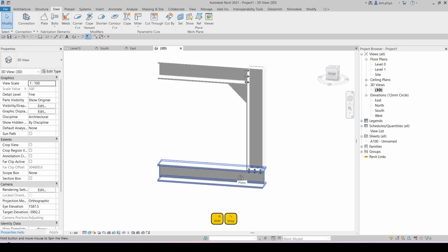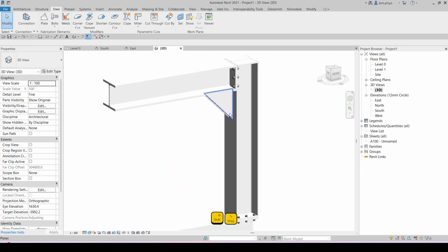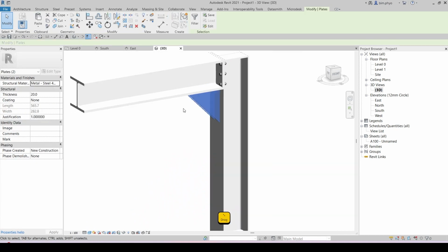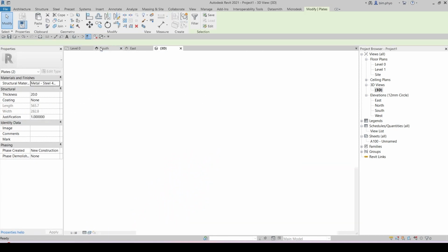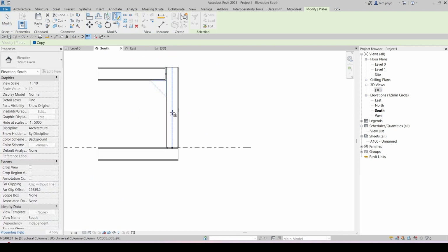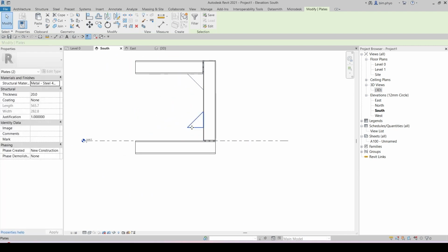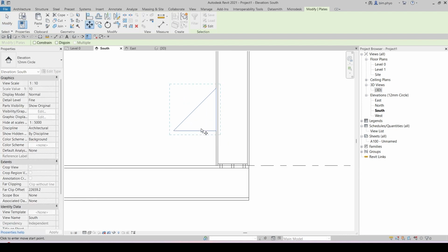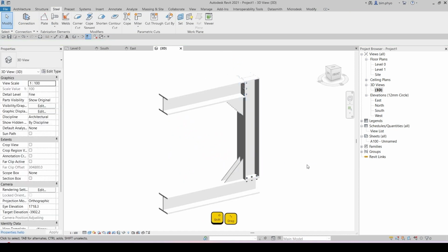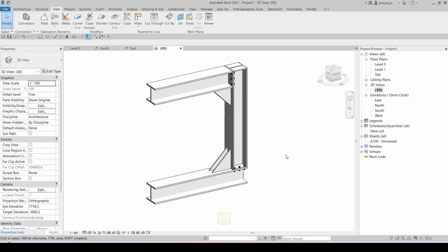But one more thing, we might need another stiffener plate right over here. What you need to do is use the slash, and then go into the sub view. Now we're going to mirror it. Look for this mirror, then select it, but it's not in the proper position, so bring it down. Okay, looking at the 3D view, that's how we can make it in your project.